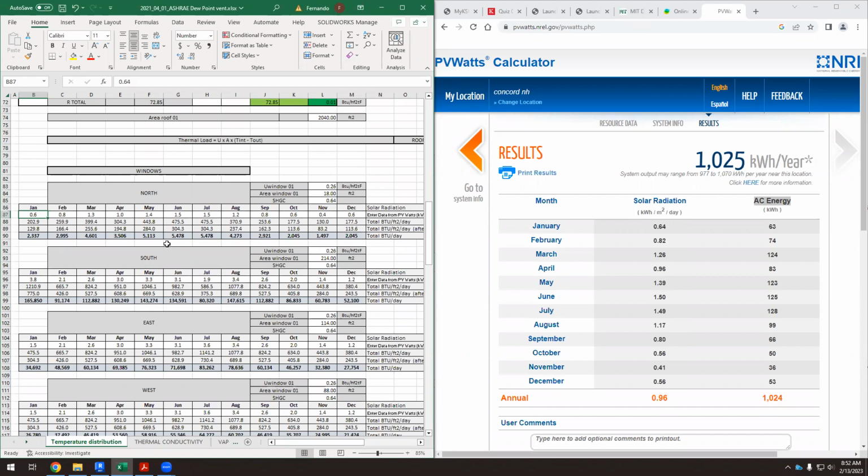With the direct light, we actually see the sun. With the diffuse light, we don't see it. Okay, it's clear, it's light, but it's not direct sunlight. So that's why even in the north, we have solar radiation. This diffuse radiation enters the building depending on the area of the window and depending on the solar heat gain coefficient.